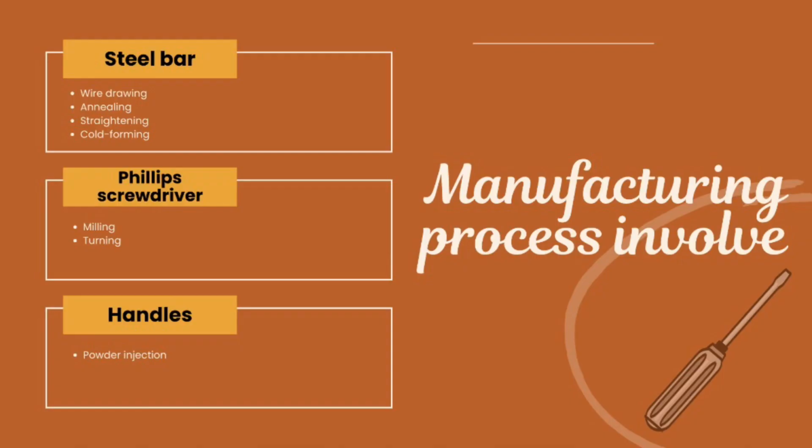Cold forming is a high-speed process that allows manufacturers to produce large amounts of metal-based products in a fast, consistent, and cost-effective manner. When compared to high-heat formation methods, cold-formed products are harder, produce greater yield, feature higher tensile strength, and have a superior surface finish.